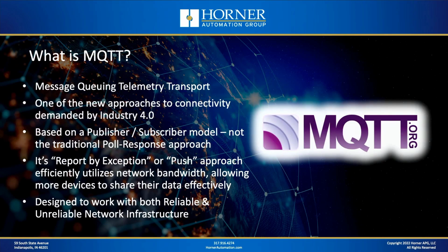With MQTT and its publisher-subscriber model, it's more of a report-by-exception scenario or a push scenario, where the PLC device itself is sending the data upwards as opposed to sitting around waiting to be polled. And MQTT has been designed using this push approach so that it works really well with both reliable network architecture, where you've got a solid LAN, maybe 100 megabit or gigabit at your disposal, or maybe where you don't have a solid LAN, where your only connection with the machine is over cellular, over a radio modem, or some other low bandwidth approach.